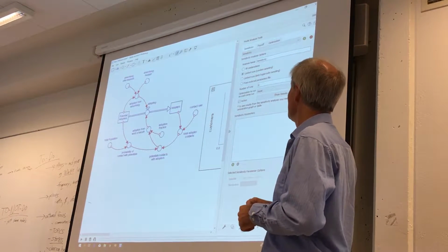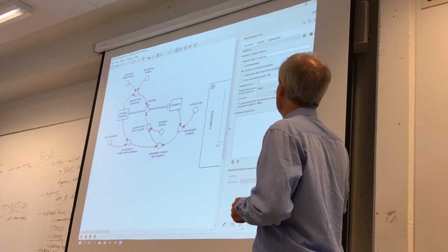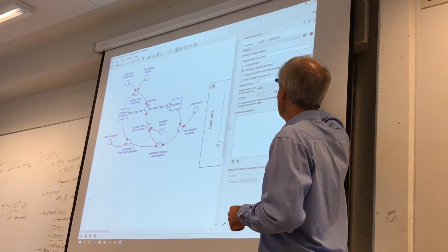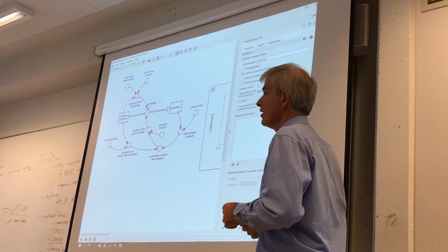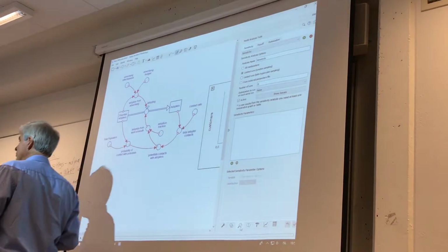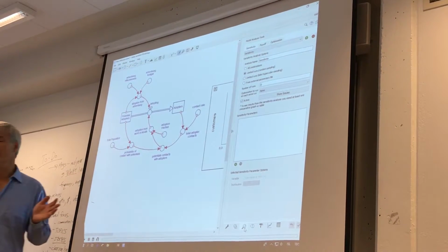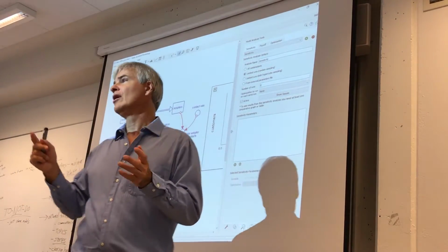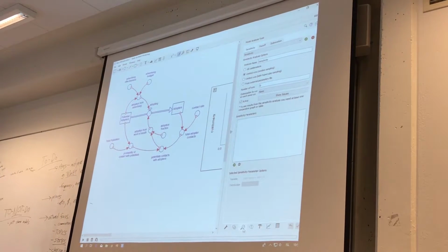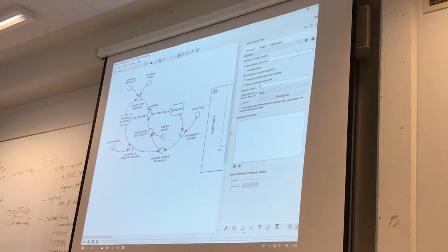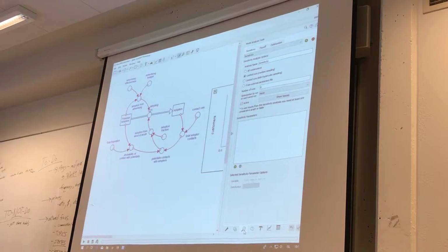So sensitivity is broken into a bunch of places. We can do a lot of stuff I'm not going to talk about right now, because we need to do other stuff. But what we will do is we need to set what we want to do here. And we have lots of options. The top option says, all combinations of all the parameters mixed together any way that we want. Well, we're actually going to just change one parameter, so that's a good choice for us. The next two choices allow you to do a random sampling from all those combinations, and you set the maximum number of runs that you want. Okay, and I'll stick to just talking about those two.